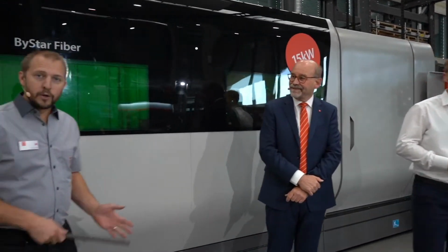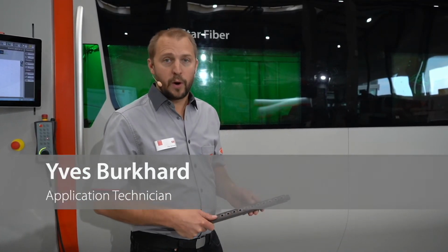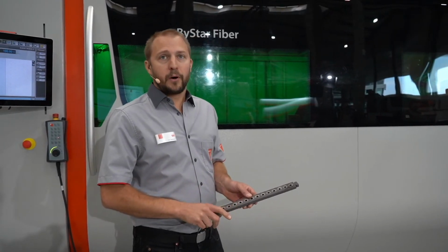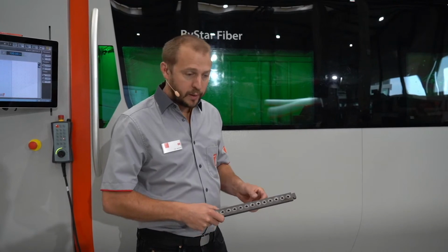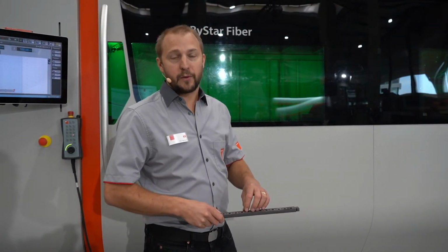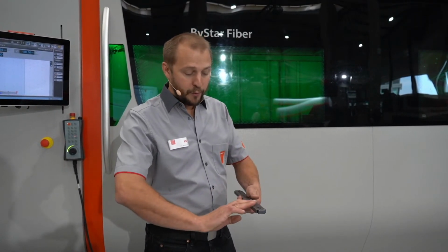Yes, so then let's see some action and cut some parts. Okay. So we will start on this 15 kilowatt with a 10mm mild steel. So this is not a regular mild steel. It is a very low quality mild steel, so no laser material. We'll cut that part with mixed gas, which means we take nitrogen, add a little bit of oxygen to it. Like this, we are going to save time. We're about 15% faster than with regular nitrogen on this part here. And we have a perfect quality, although it's a low quality material.